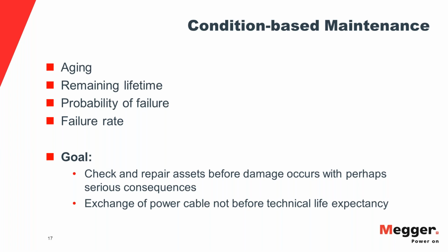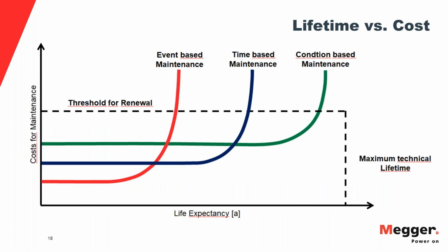If it's not necessary, because you say, XLPE cables, you should get 40 years out of it. That's typically the nominal life expectancy for design, or maybe even 50 years. But for instance, it's expected that you're probably not getting the same life out of the extruded cables like we did out of the PILC cables. And then this is pretty much the investment side of it.